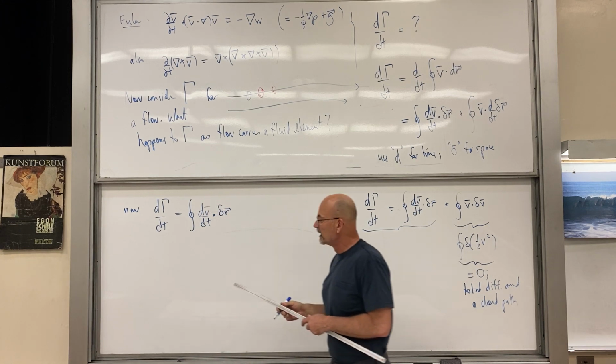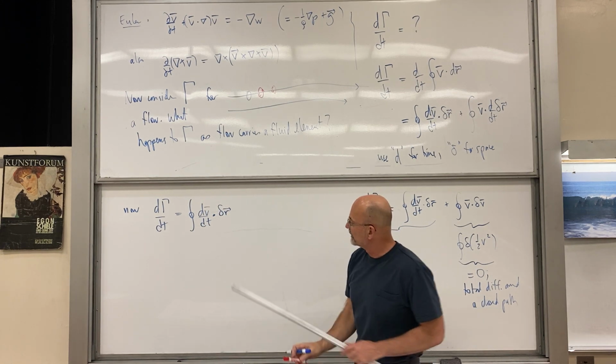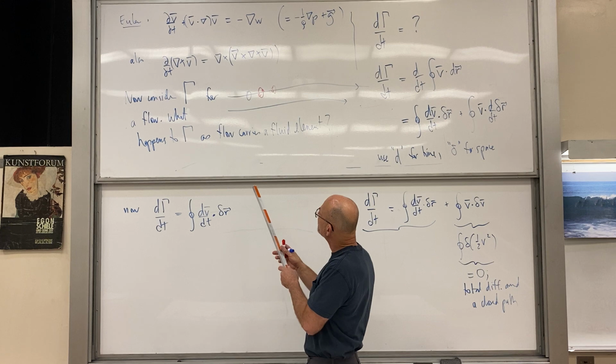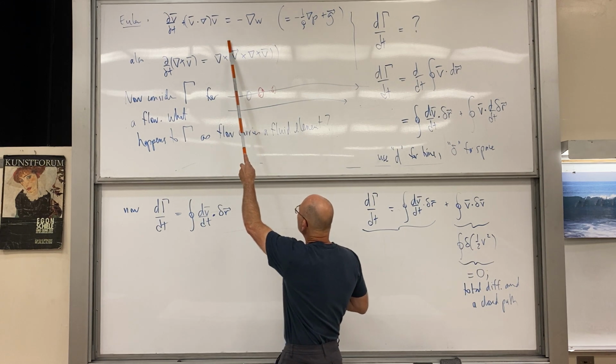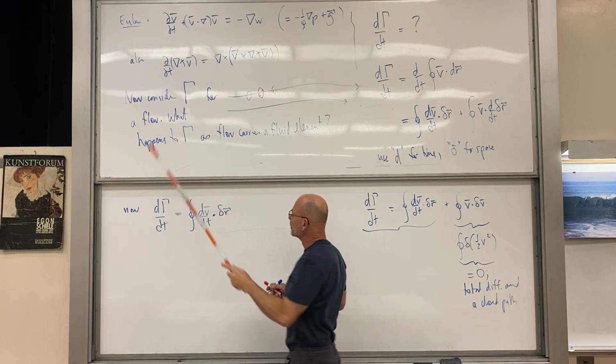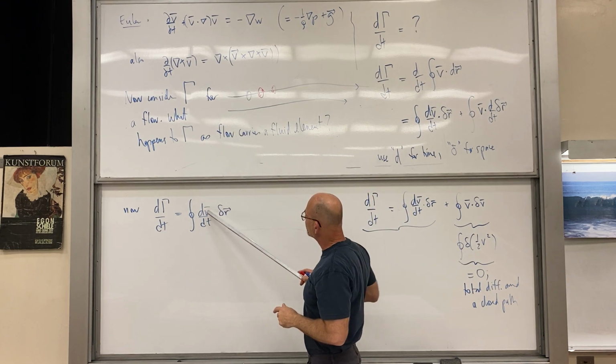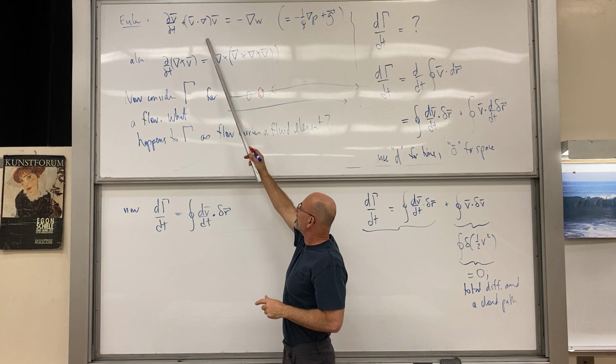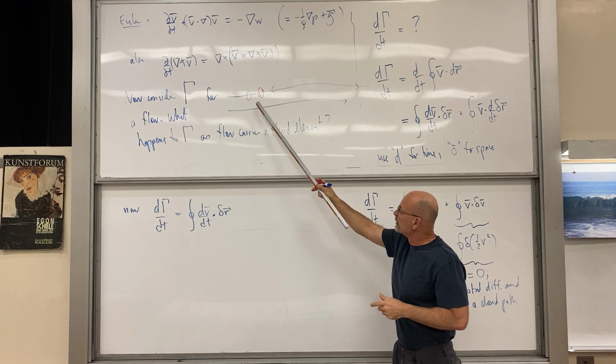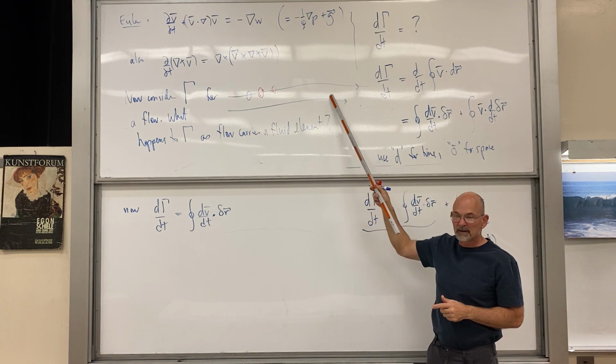Okay, what we're going to note next is that this complete time derivative is really the entire left side of the Euler equation. Remember when we transformed to the field point of view, we went from here to here, but now we're asking about the element of water being carried along. Okay.